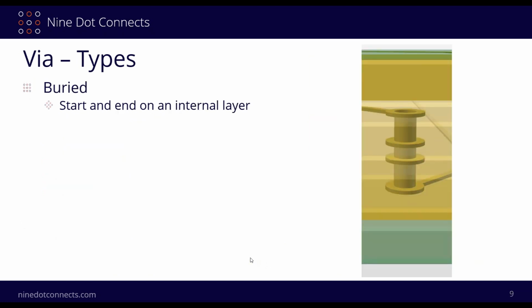The other one over here is the buried one. So we don't see this thing. It's completely encapsulated in the solder mask and in the buried layers of the PCB design. Okay. What are their advantages? Certainly, again, no or less stubs. So again, be careful. Just because it's smaller does not necessarily mean that we couldn't still create an opportunity for a stub. And the big thing, of course, is that you're gaining real estate, usually both on the top and on the bottom. So if you're doing a lot of routing, these things are very, very useful.